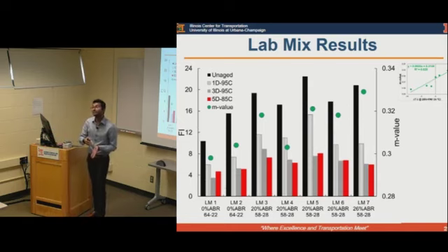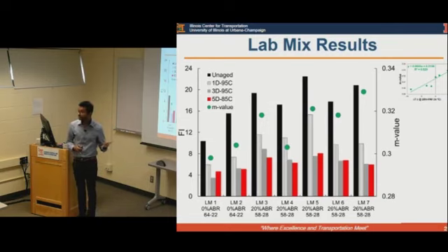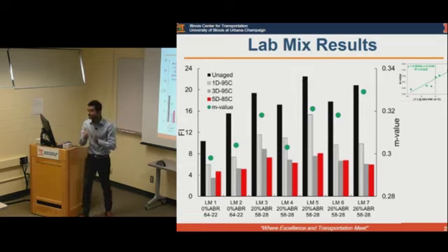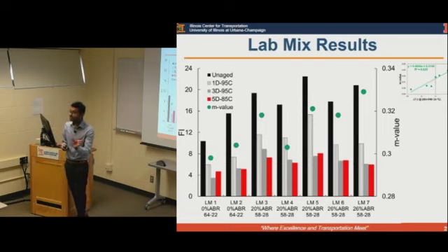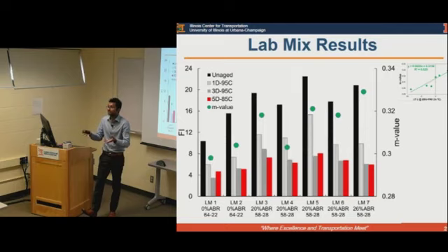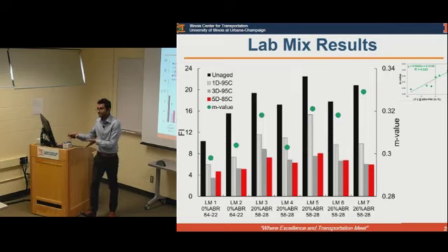But whether UV is just heating or causing that reaction, I still don't have an answer to that, whether UV is causing the heating. But most likely UV is an energy source which hits the asphalt material and makes the process happen. Based on the literature, they define photo-oxidation as happening because of the wavelength of the light hitting the material, and that's what makes this reaction possible. And thermal oxidation is something else, where just because of the heat you have some energy, and then the oxidation takes place.